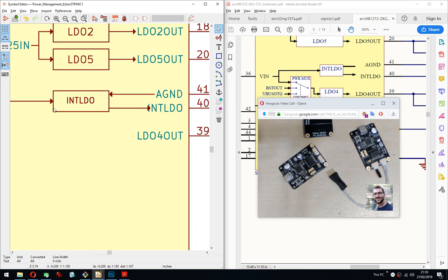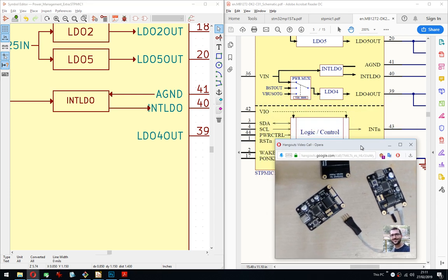The other one that has a small black part sticking out, it almost looks like an antenna. It's wireless CAN or something. Yeah, that's a termination plug. That's basically a 120 ohm resistor on the CAN H and CAN L lines. Yeah. So there is something there, nice.